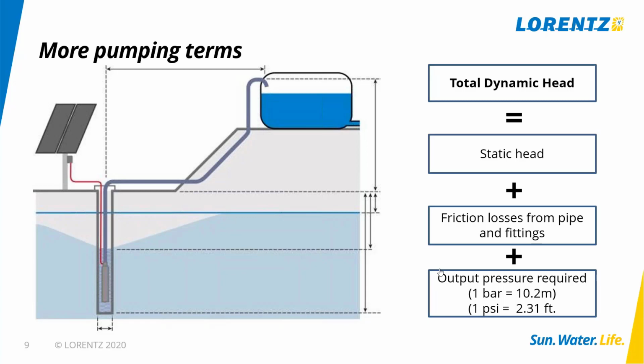So by taking the static head, and then if we need to add any output pressure, we can add that. What I would typically do is let the friction losses be calculated by Compass for most simple pumping applications. If you've got a very complex situation, you might calculate your own friction losses. If it's a relatively simple one, I'll show you, we'll do that directly in Compass.